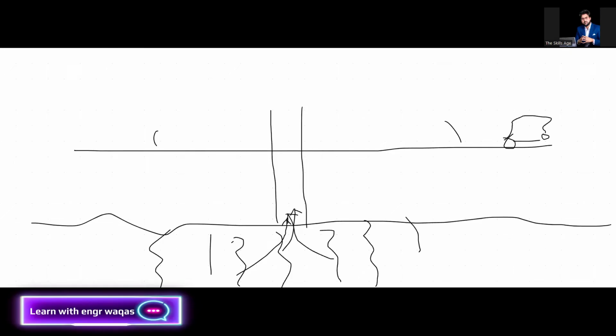This is the drill pipe completion geometry. On the top surface area, there is one tool installed, called the wellhead. It has different kinds of valves like the production valve, kill valve, swab valve, and master valve. When oil and gas flows up, it goes through different production lines. There are different vessels attached to it: a choke manifold, a control station controlling it, ESD we can call it, and then knockout drums, then the storage tank, then more production area, then ultimately to the refinery.